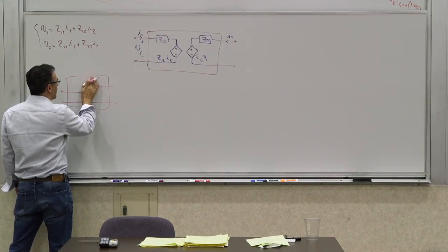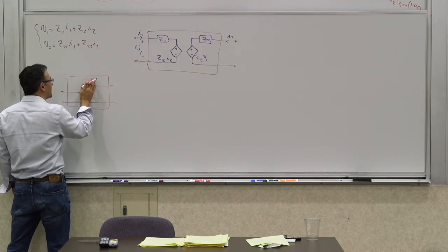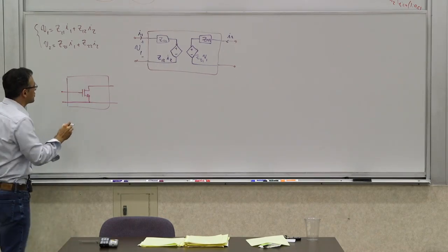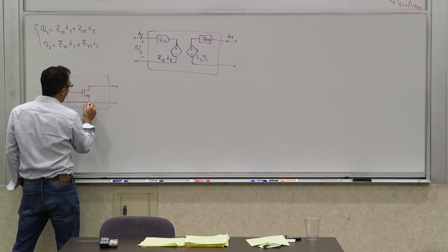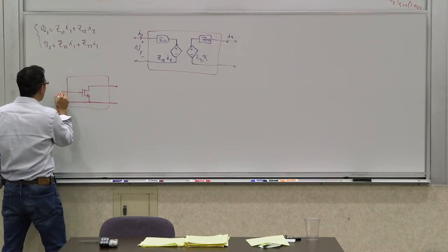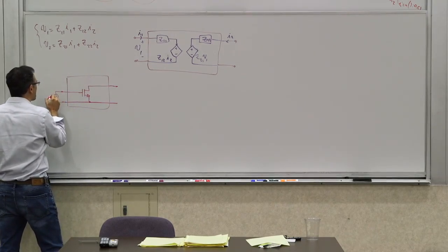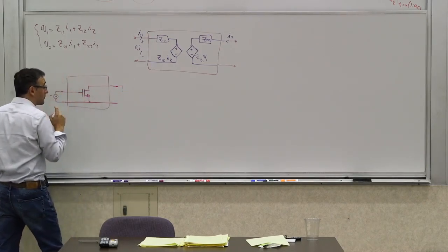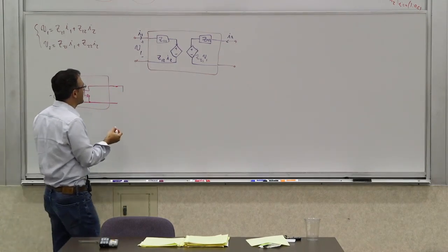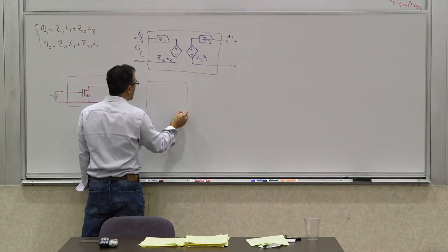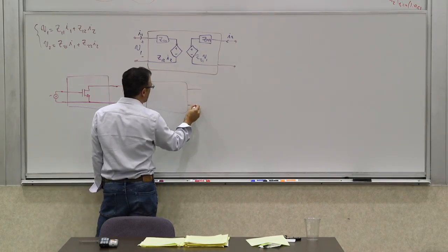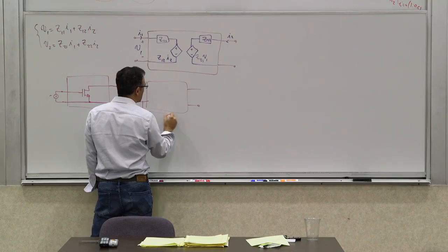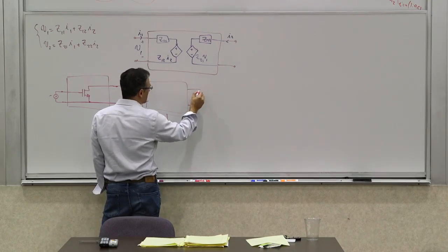Let's say you're characterizing this device when it's operating and biased at the right place. So if you think about this, really what you have is a common terminal, and as long as you can apply the right source at the input, and then you characterize it at the output, you can actually characterize it with a 2-port. And in some of these cases, your 2-port becomes a special kind of 2-port, where you are connecting these 2 terminals to each other to form the third terminal.